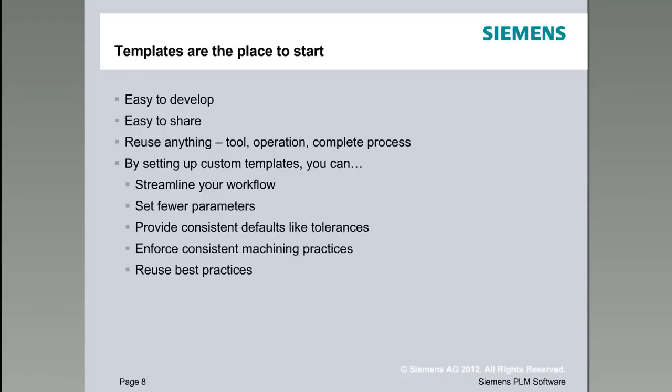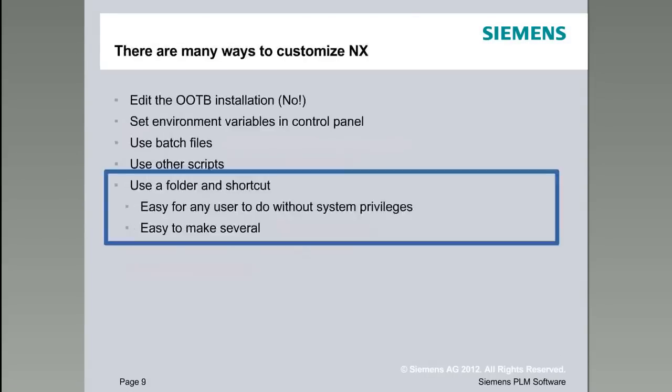You can adopt your company standards into the templates. And through using these process templates, you can enforce consistent machining practices. So everybody roughs with the same stock, followed by finishing with the same amount of step over, whatever you want to do. So it gives you a pretty good way to do this, all without doing a whole lot of code. So really a good CAM programmer can go in and do templates. This is why I think this is a really good place to start. As far as bang for the buck goes, it's a really good investment.